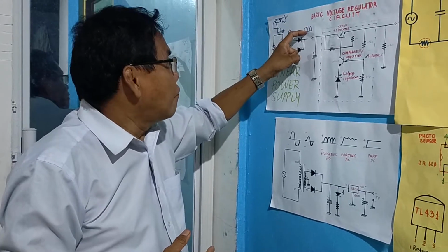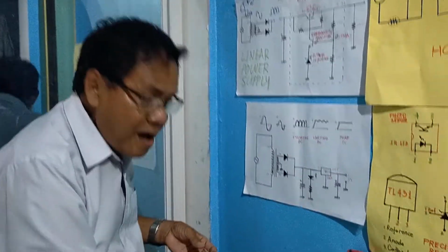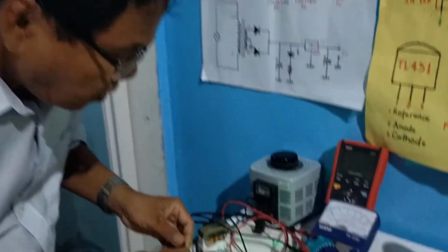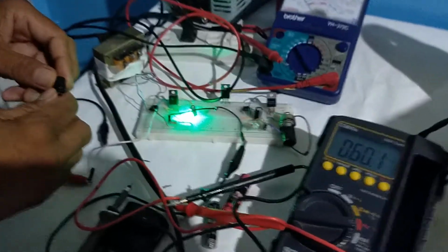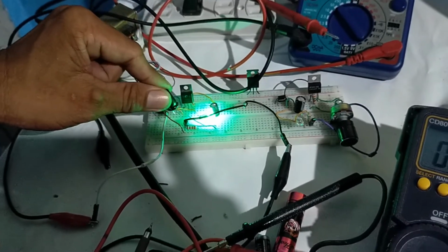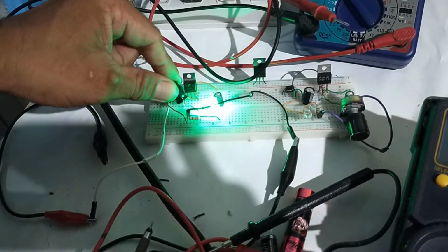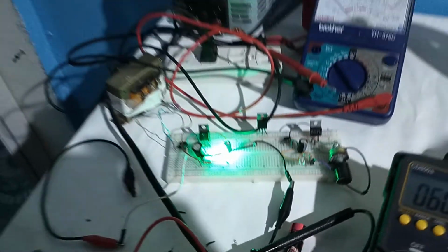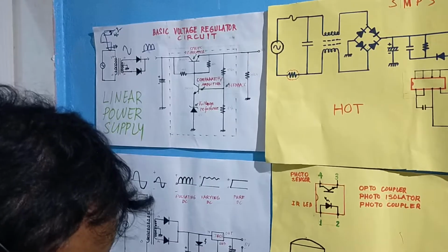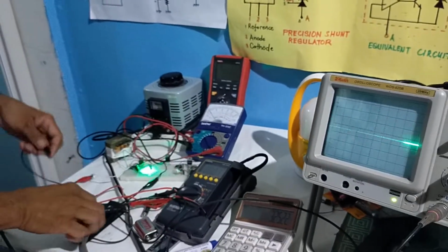12, 8, 12, 8, 12, 8. A matter of 4 volts variation. So we need to smooth out that using a capacitor to filter out that variation of voltage to eliminate hum. So let us connect this filter capacitor. Just across here, and let us get the frequencies of the signal. Okay, let us connect.